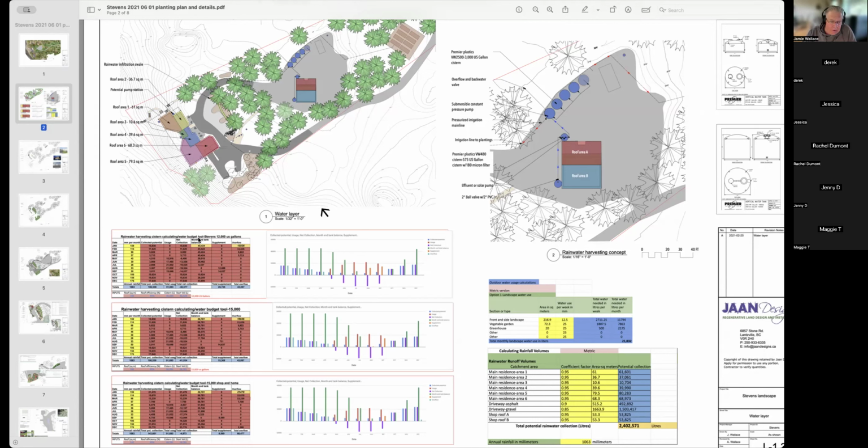So you can see in this calculation, with 12,000, we had about 26,000 liters that we have to supplement. Whereas if we bump up our storage to 15, and then collect off the house and the shop, we're only having to supplement, that looks like 8,500. So it's a great tool because we don't have to guess. We can roughly calculate usage, and that is going to change month to month. So May's usage is going to be different than August.